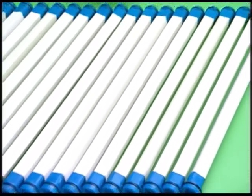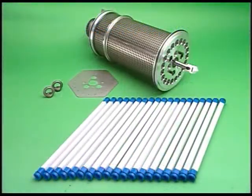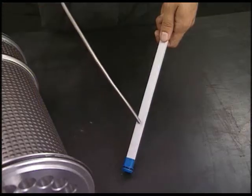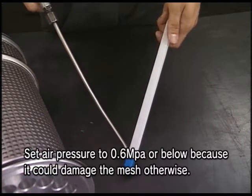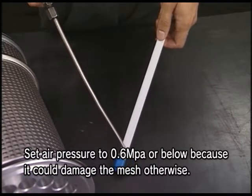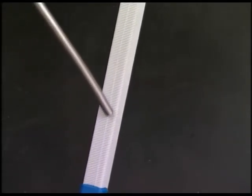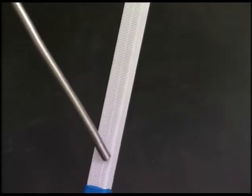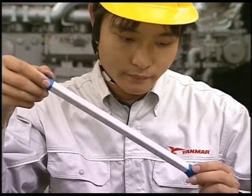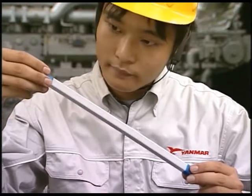Leave the pulled-out filter element soaked in the cleaning agent for 24 hours. Conduct the cleaning by blowing compressed air from the outside of strainer element. It is more effective to use hot water of high pressure instead of compressed air. Conduct the visual check after cleaning. Replace any parts with scratches or dirt.